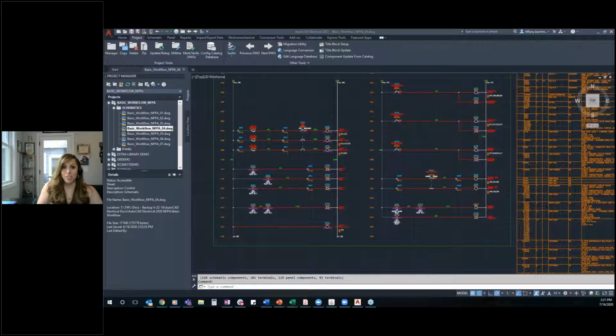This is not that. I often get people from the AEC industry looking to utilize even AutoCAD Electrical. They see some of the benefits and ask me, hey, can we use it for this? I typically steer people pretty far away from AutoCAD Electrical for that. There are a lot of ways to bend electrical into different industries, but when it comes to AEC, you're far better suited to use AutoCAD MEP or the MEP tools out of Revit. And it sounds like you're already a Revit electrical user, and that's fantastic.